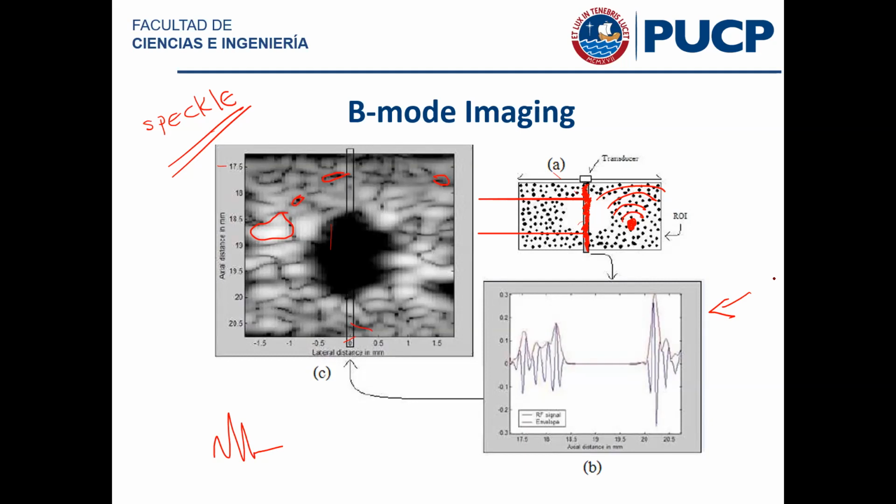Okay, so the envelope function works to determine where the peaks are. Not the peaks really, but what the envelope does is it removes the oscillatory behavior. The ultrasound transducer will oscillate because that's just what it does. But displaying the amplitude of an oscillatory signal would give you horrible variations. The variance of the signal would be horrific.